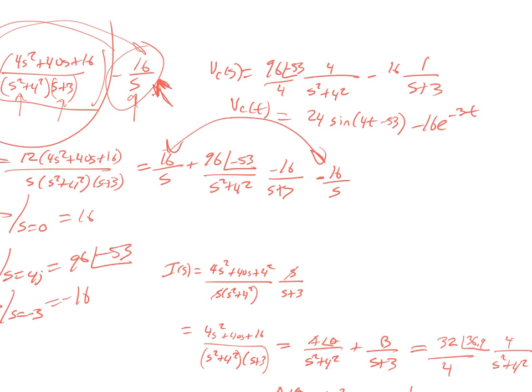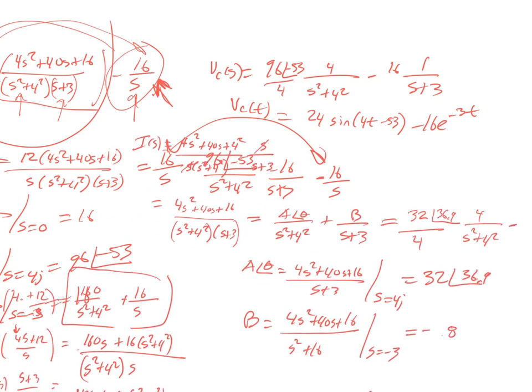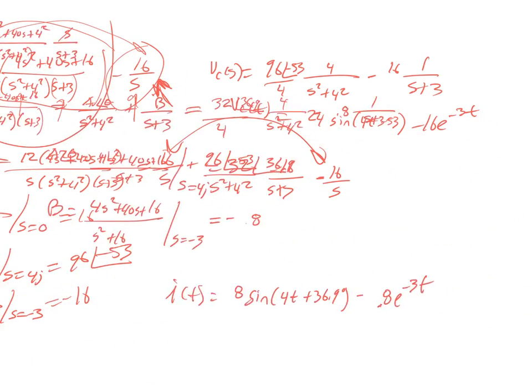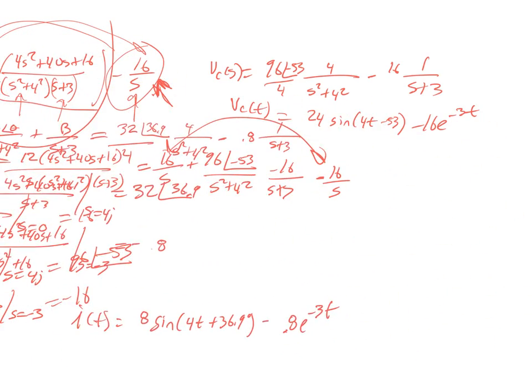The current has an angle of, here, right? Its angle is positive 36.9. This angle is minus 53. So the current, if I was going to draw a phasor diagram, is here. This is I. The voltage is down here. This is 90 degrees. You could also check, if you plug in V at time t equals 0, you should also get 16 volts.